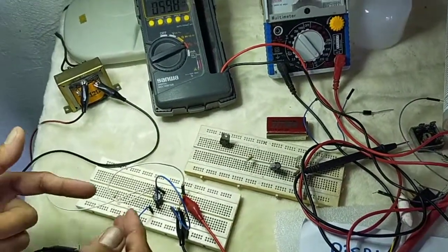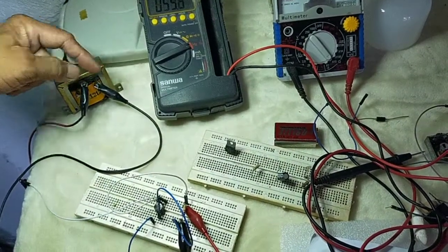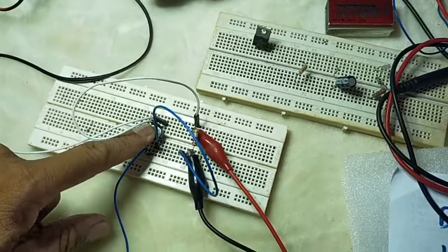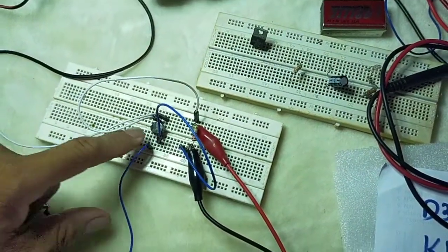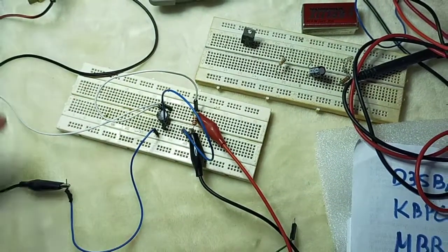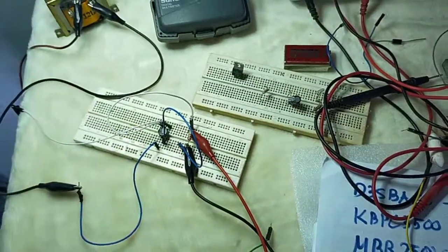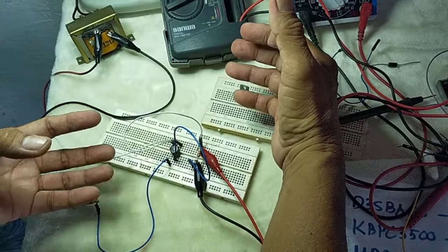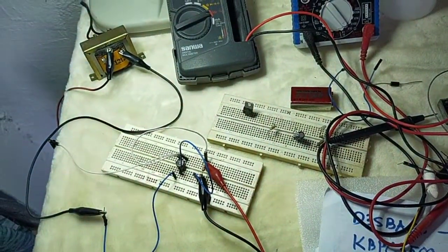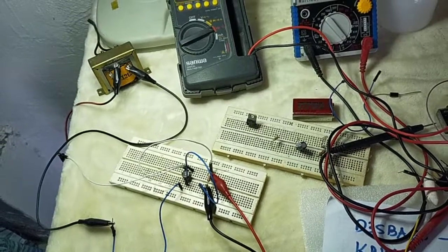Whereas, for the bridge, it uses only 2 terminals. However, although bridge is a little bit expensive because it uses 4 diodes. No? Anyway, you can use either of these two because these full wave rectifier circuits are applied to any electronic equipment, electronic appliances.